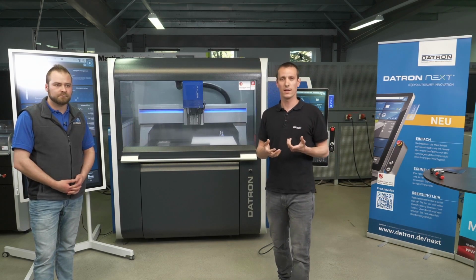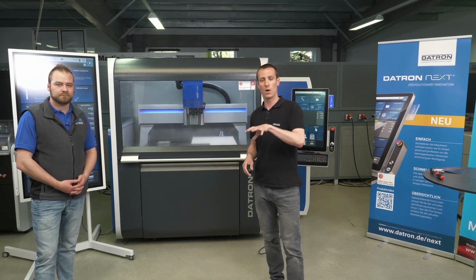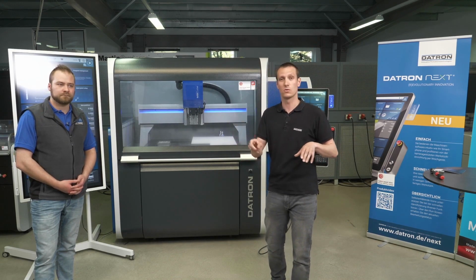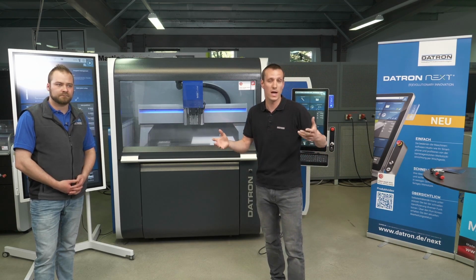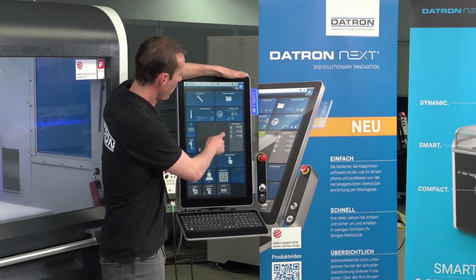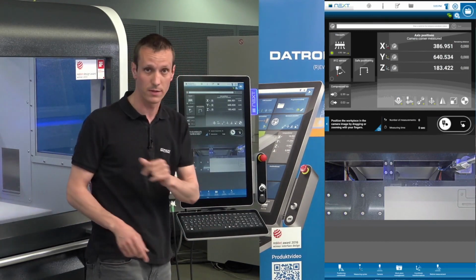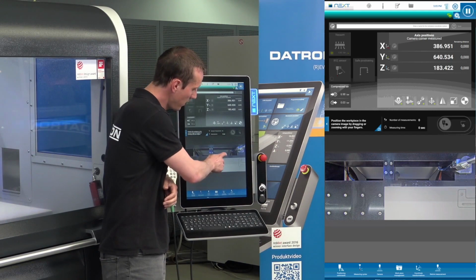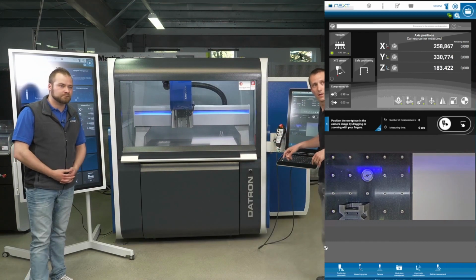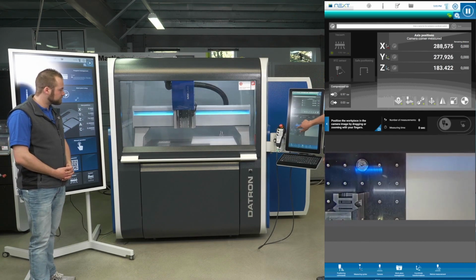It's measuring the origin and the orientation in that entire machine with a camera, with a live view, just by swiping over the display and then drawing a shape around the part, whatever it is. So let me show you this. You go to Workpiece setup up here, and now I have a live view because there is a camera right on the Z-axis. So if I just drag over here, the machine moves, and let me get a little bit out of the way, I keep dragging around and you see the machine just follows where my finger goes.